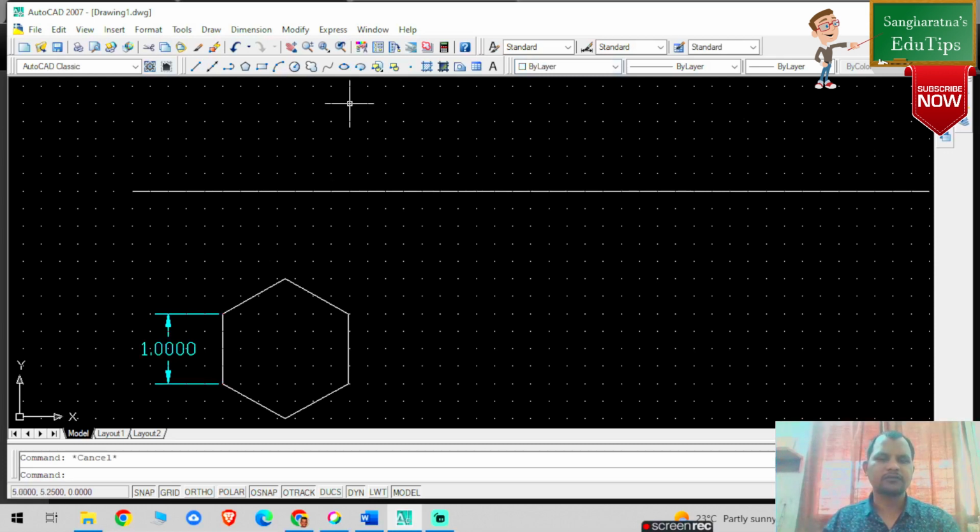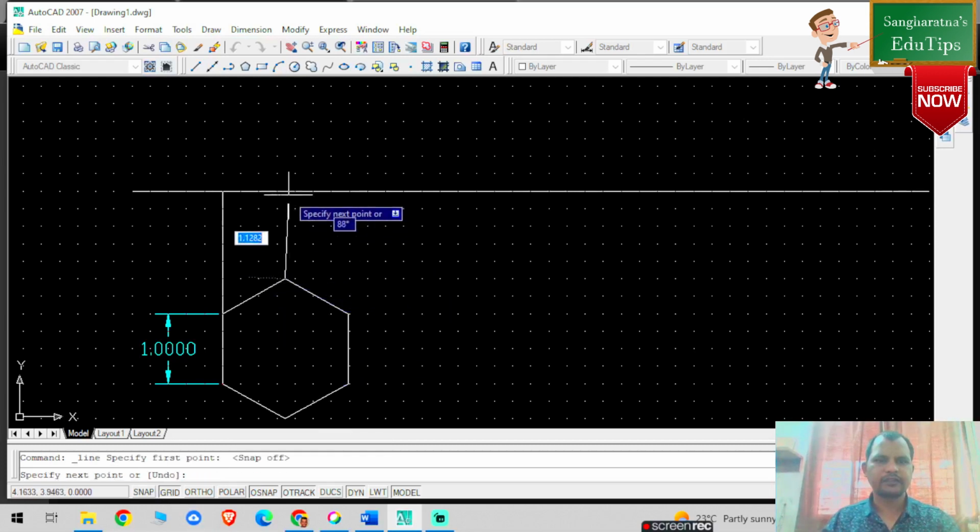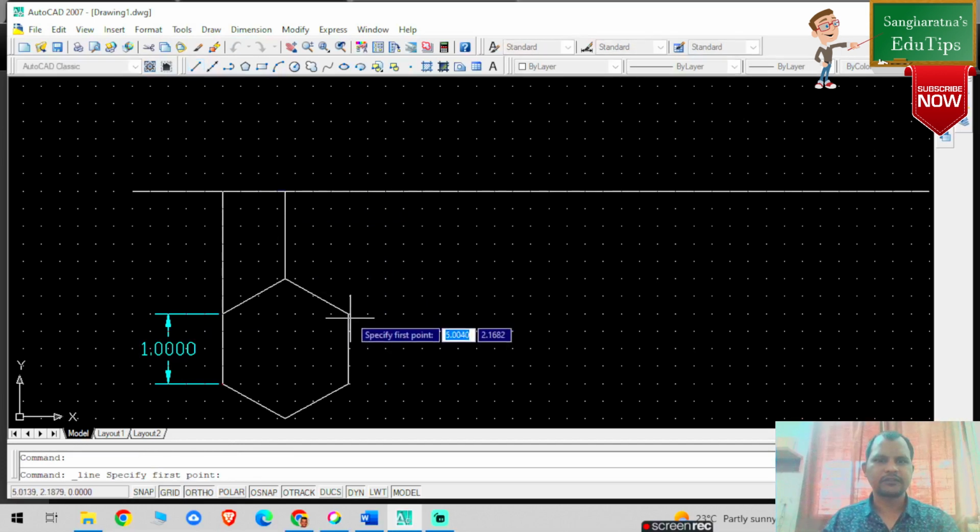Okay, now what I need to do is I need to project this particular line in the perpendicular direction, so I'm selecting ortho from here, right, and then projecting here. Escape, Control Z. Okay, this is not perpendicular, so this is one of the points. Okay, so click on snap and click on ortho. It's another projector line. This is another projector line.